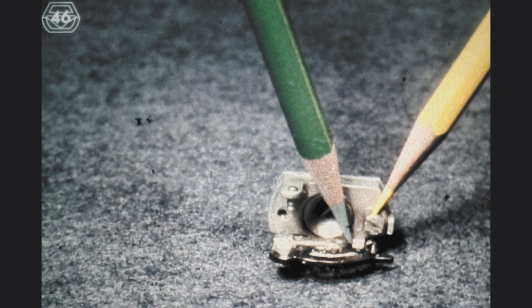The adjustment can only be performed satisfactorily when the ring is reassembled in the typewriter, and it is possible to test the side play of the element. One of the reasons for this is that the rotate detent does not move quite all the way up to the underside of the tilt ring when the element is in place. You should not be the least bit surprised if you need to spend 10 to 15 minutes on this adjustment when you try it for the first time.